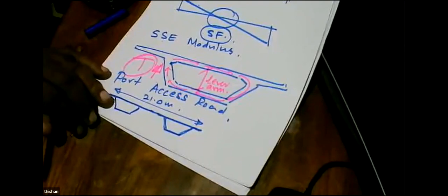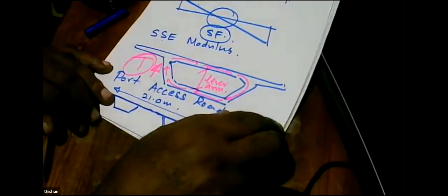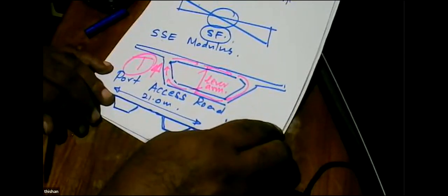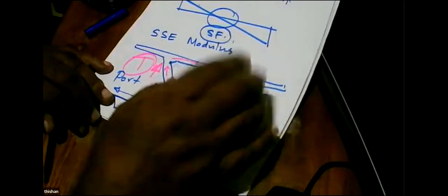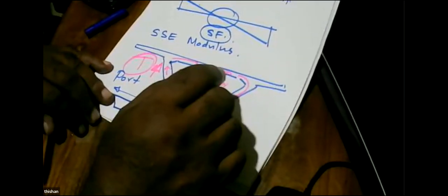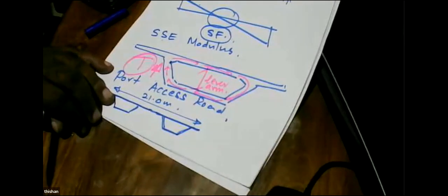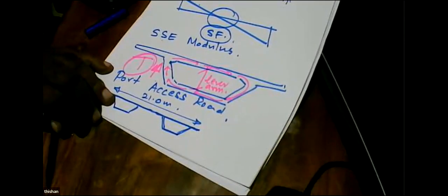So when you are using this in a highway bridge, these beams can be subjected to a certain amount of torsion, and these box girders are super strong in carrying torsion. Because of that reason, for larger spans like 40-50 meter spans, these box girders are preferred over the I girders.